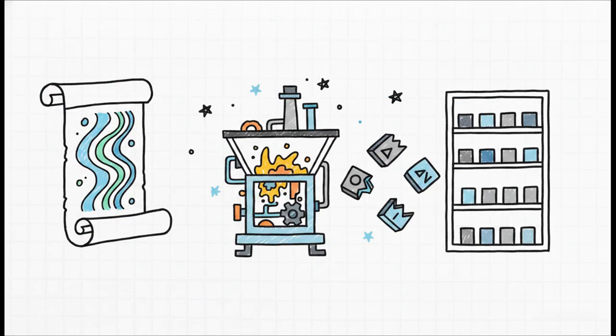Once that RTL code is thoroughly verified, we move on to a complex technique called synthesis. The EDA synthesis tool acts almost like an automated genius translator. It takes your abstract hardware code and maps it directly to a library of standard cells provided by a manufacturer. You can think of these standard cells as pre-manufactured digital Lego bricks, your AND gates, OR gates, and flip-flops. Synthesis translates abstract-coded behavior into a hard, physical blueprint of actual logic gates.